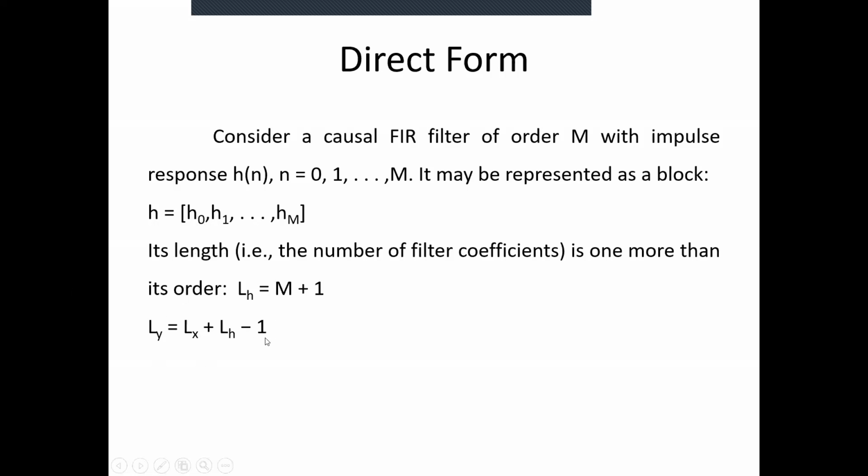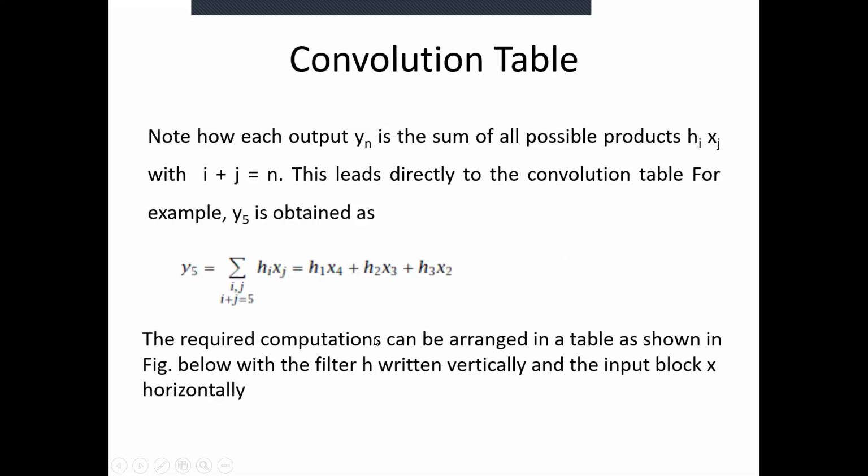Again, you have to keep in your mind this equation. This equation is very important: Ly equals Lx plus Lh minus 1. I mean, the length of the output, how many coefficients we have in the output, will be Lh plus Lx minus 1. Again, we are going to utilize this equation in the next coming slides.